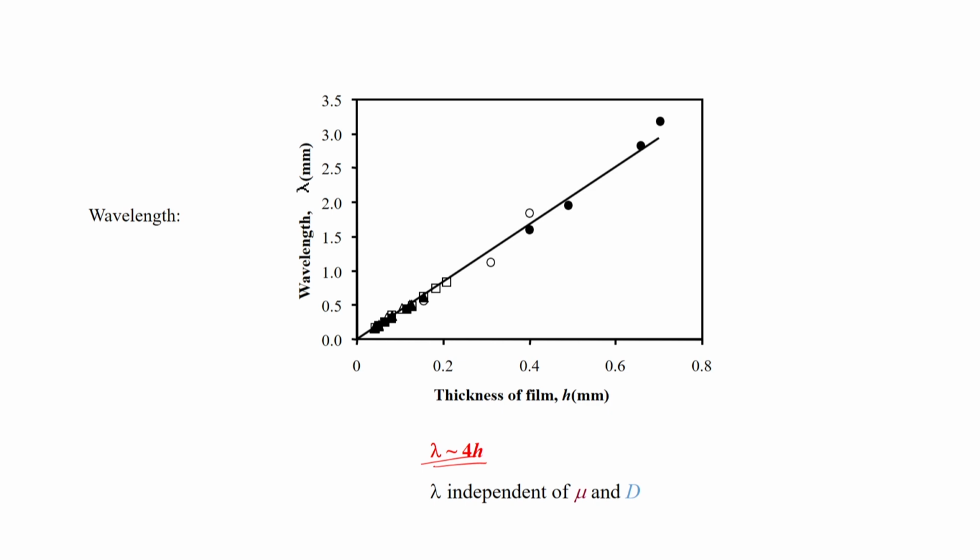This is a very generic relation that we get for this kind of incompressible elastic film in this rectangular geometry, and lambda remains independent both of the material properties of the adhesive film and also of the flexural rigidity of the flexible adherent from the top.